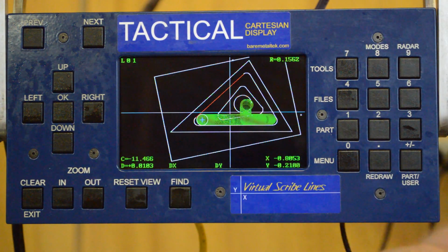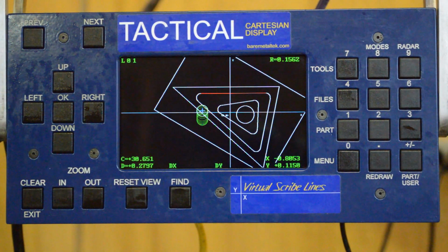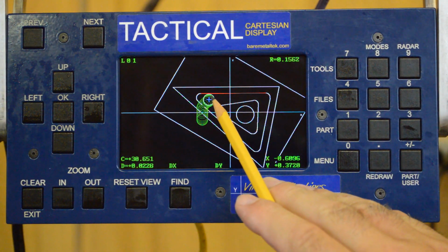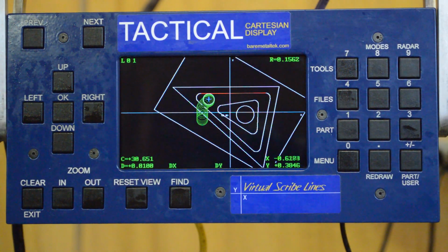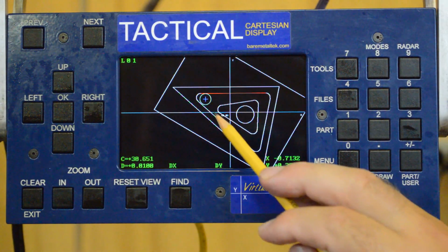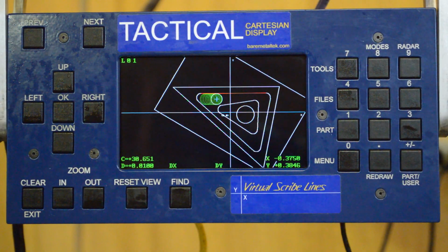Now I'm going to make this parallel to X. All right, get the tool back down into there. Get myself to within 10/1000ths of that wall. Now I'm going to feed into this corner. I don't have to be as careful this time because most of that metal's already out of there, so I can just visually go by the lines. Now, that's a good place to stop right there. Now feed along this wall.